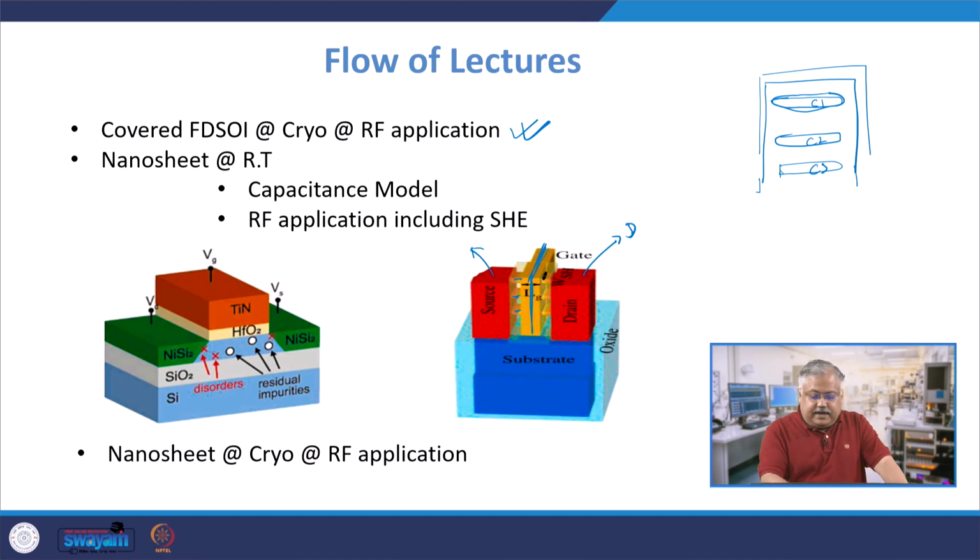And on the left and right hand, this cross section which I have drawn here is by cutting it from this axis. So if I assume this to be x bar, basically cutting through x and bar like this, vertically cutting it, and then if you look from this side, then this is the structure which you will see. And there will be 3 channels across which the current will flow. The gate is the yellow one which is given here, and the gate is responsible for all sorts of biases for creating an inversion layer in the channel.